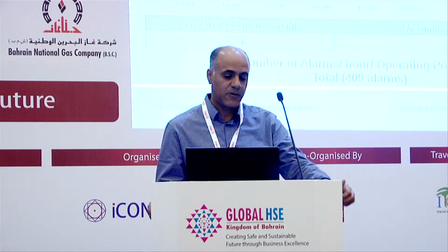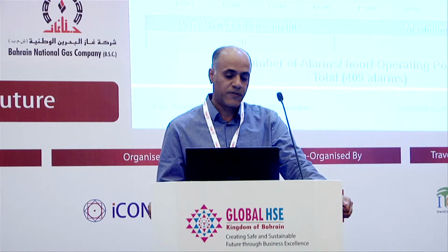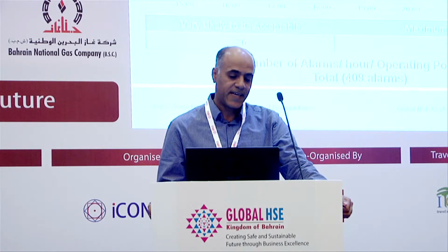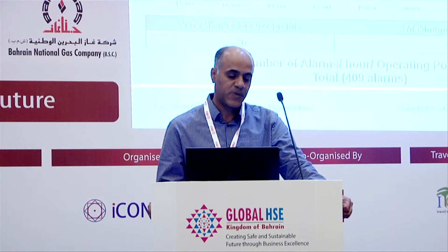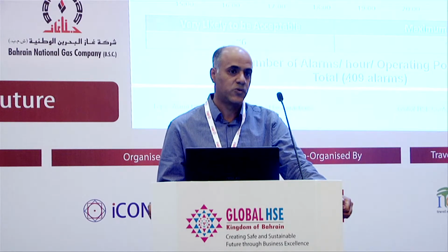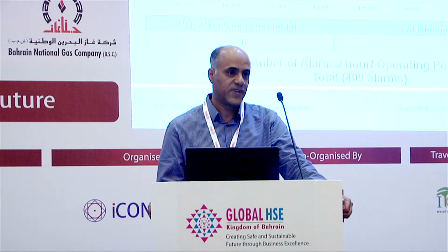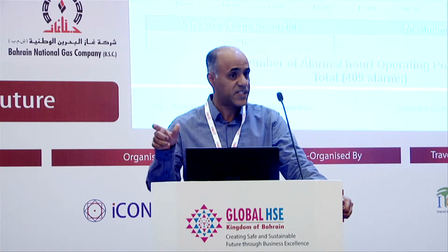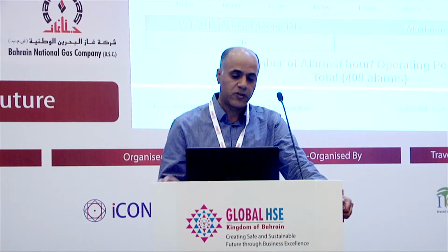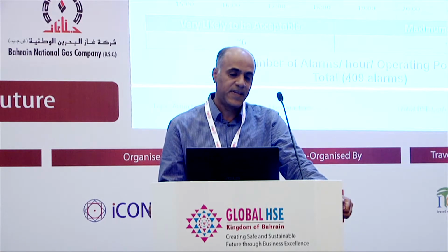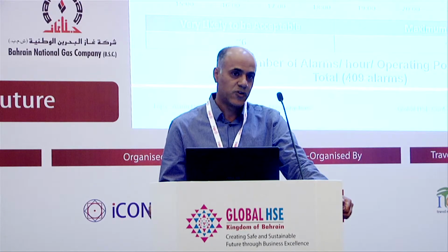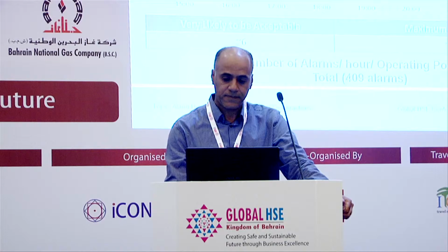We can see that the 8-hour afternoon shift scored a very high number of alarms against the recommendation of the standards, which says the maximum manageable alarms per hour is 12, taking into consideration that the operator has to read the alarms, investigate, and take action, so that needs some time. But I can see at 10 o'clock, we had 83 alarms generated, which is far above the recommendation of the standard.